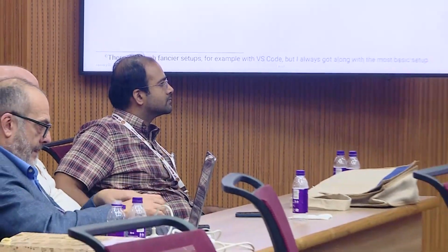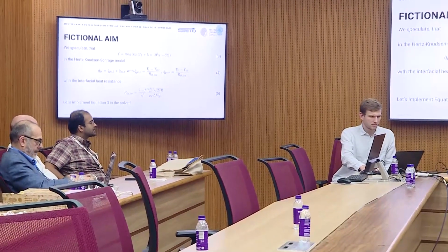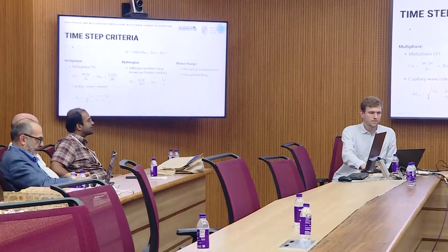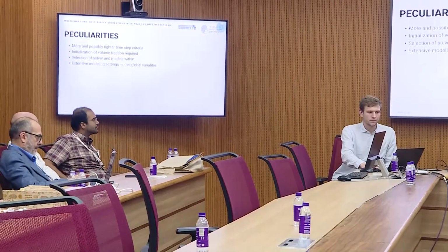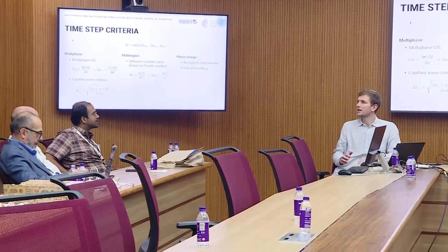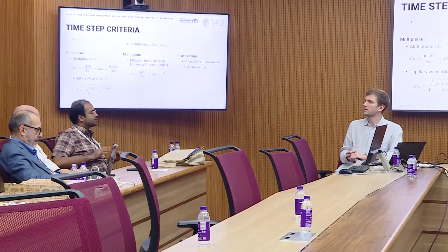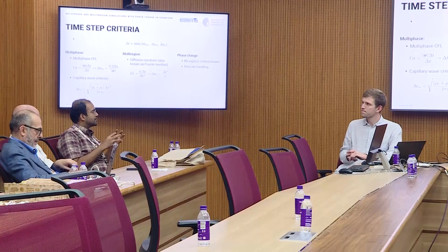Should I strictly satisfy the CFL criterion, or how does it become numerically stable in this case? I would say if it is pure diffusion, you use the diffusivity, or if it is pure advection with a bulk velocity, you use u delta t over delta x, but you do not have a bulk velocity, just a small deformation.